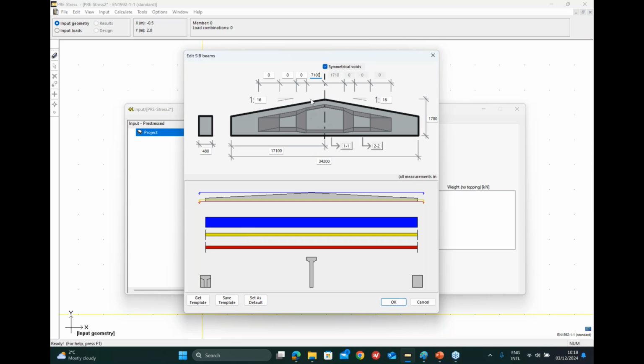And this is the way how you can customize your sloped I-beam. Now, in the same principle, I can play with all the dimensions here. I can extend this transition zone. I can make, as I said, a slimmer web, then increase it, or whatever I want with it. And this is a better approach compared to using custom sections.